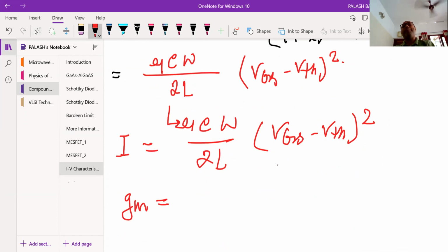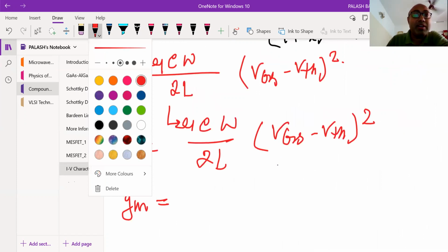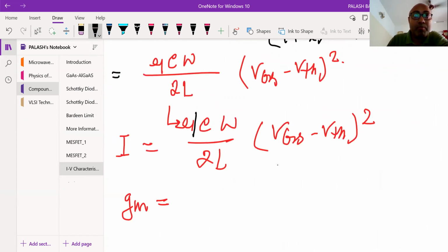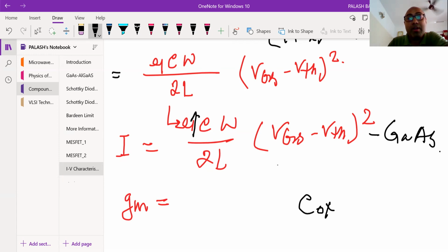What about my capacitor? So here mobility is very, very high. That is actually our discussion. We end up with mobility is high. If you are taking gallium arsenide, it's further high. What about my capacitor? Capacitor for MOSFET, if you remember, that is actually epsilon by Tox.